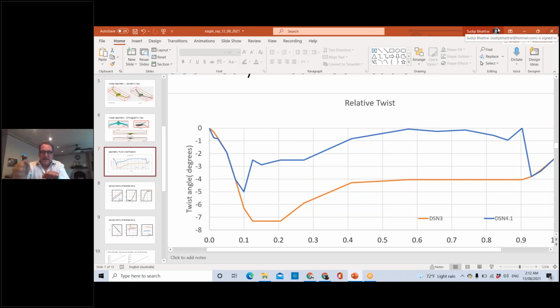So if at this condition my stall speed was 40 meters per second, here my stall might happen at 45. I'll stall earlier, so-called accelerated stall, because I'm pulling G.